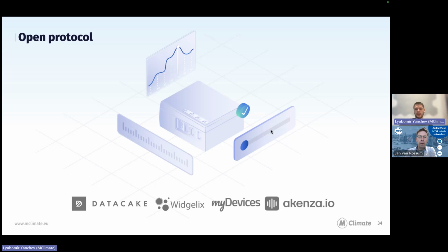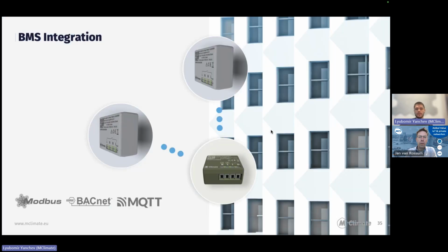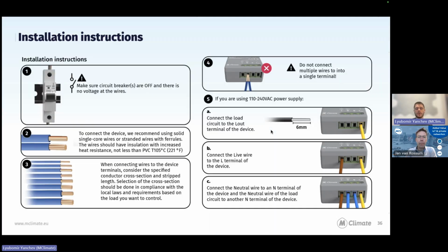Both devices have their protocol fully open and well documented, and if you have any questions, our support people are ready to help you. Again, both devices can be used for direct integration into BMS, so that they appear as a BACnet device, or a Modbus or even KNX at this moment.